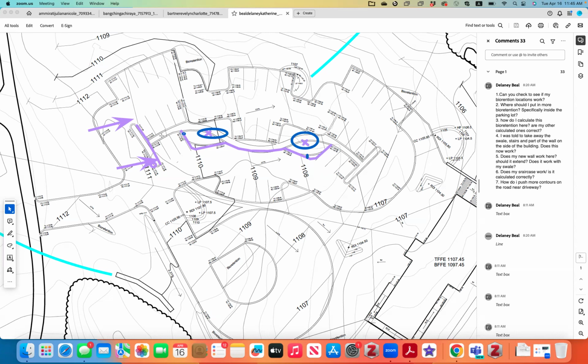So in that case, in order for it to not create more confusion, you would turn the segments that are this sidewalk, the bottom ones, you would design exactly the same as the other retention area. You would turn the line type to a dash line here.